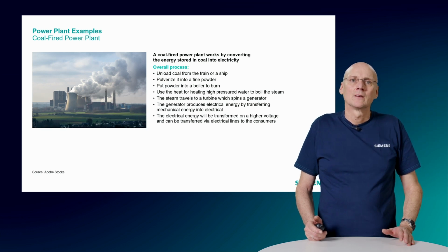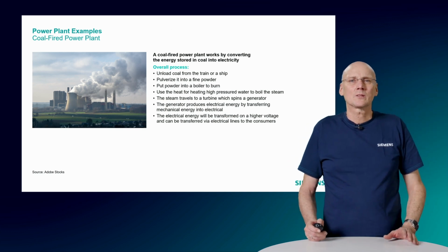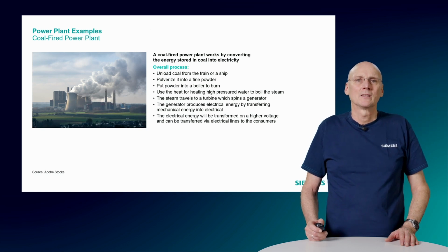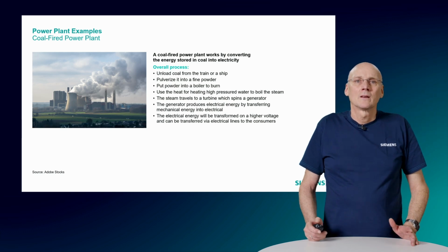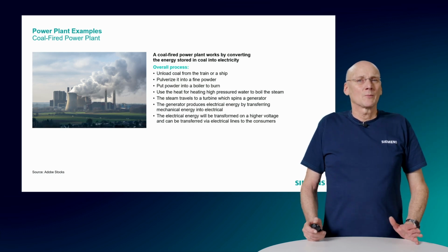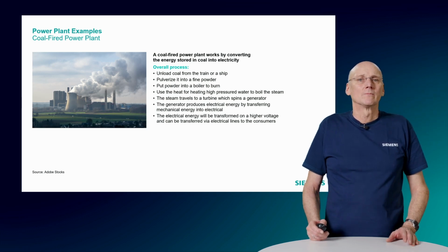The transformer ratio formula to calculate in the easiest way: power equals voltage primary side multiplied by current primary side, which is equal to voltage secondary side multiplied by current secondary side. And from the secondary side of the transformer, the energy will be fed into the transmission lines. Remember for a later module: transformer protection and line protection functions.